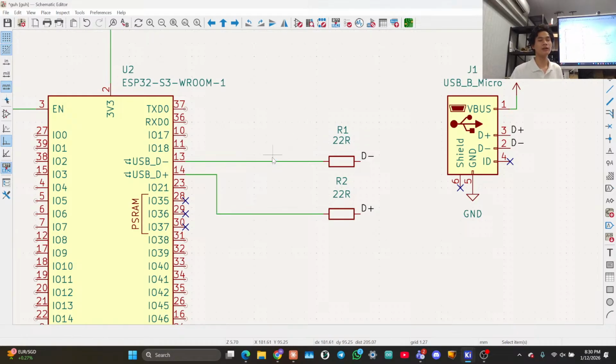Okay, so normally when you have a binary signal, it'll be high and low, right? So the line will just be at 3.3 or at 0, for example. But here in a differential line, which is a pair of lines, we care not about the exact voltages, but the difference between them. This is good because I route the differential pair right next to each other, and if I apply some external EMI to the thing, then both of the voltages will rise, which will not affect my signal because the difference between them is the same. This is what a differential pair is.